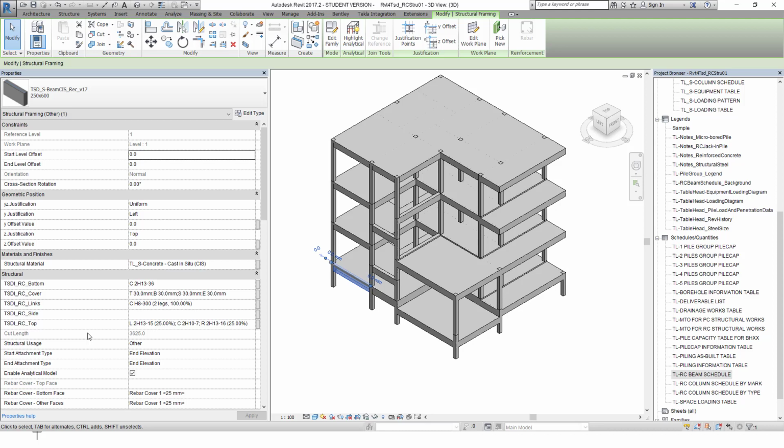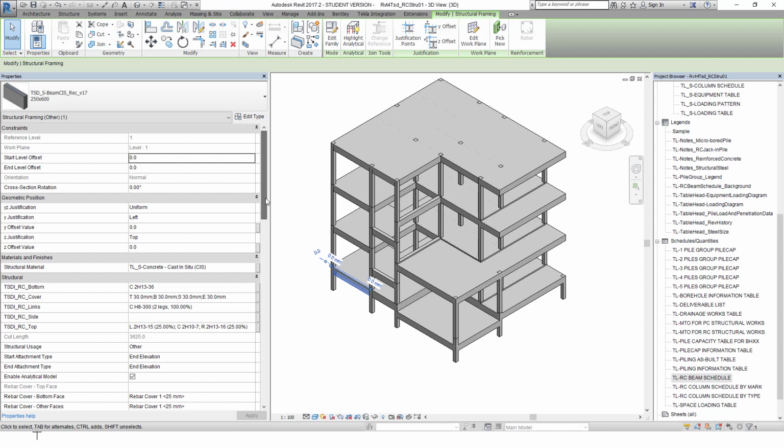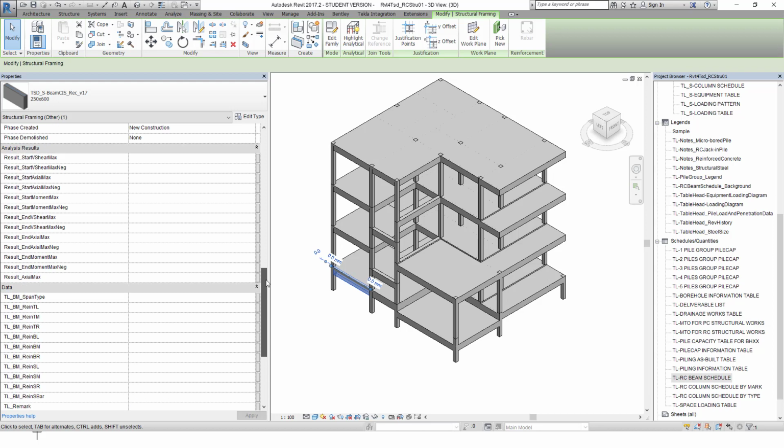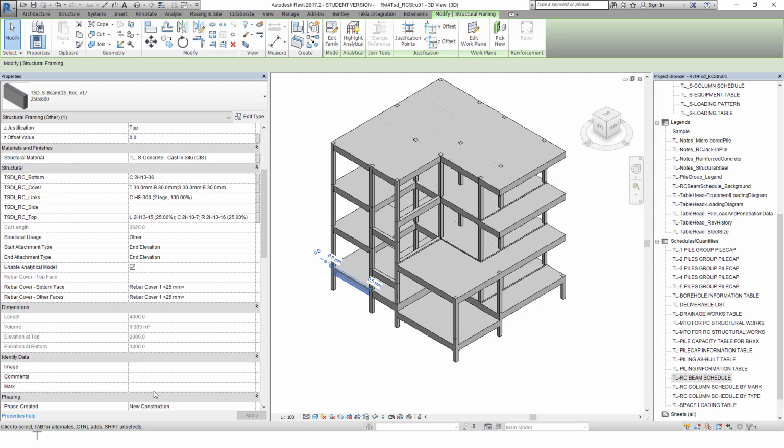Another thing is the top bar, also the same thing. They just put the top bar with left, center, right all in one piece of information. So as a consultant, we need to split it into three: top left, top center or top middle, and top right. If we do that process manually, it's really very tough. And some more, they provide the percentage also. This percentage we don't need, so we will remove it and put the full value. Then beam marking also comes along with the model. You can see over here, this is a part marking. We call it a beam marking. This marking we also have to reflect in our Revit beam marking.